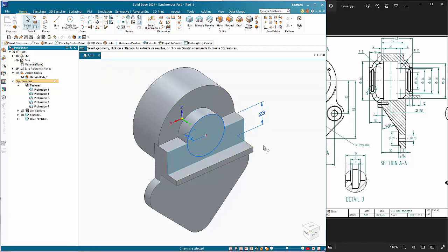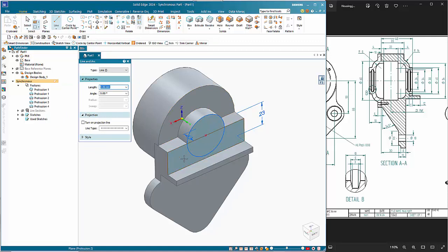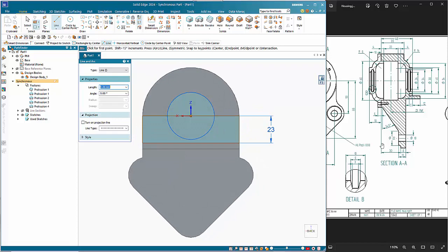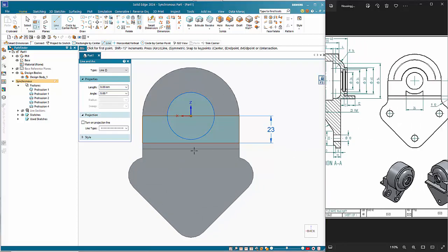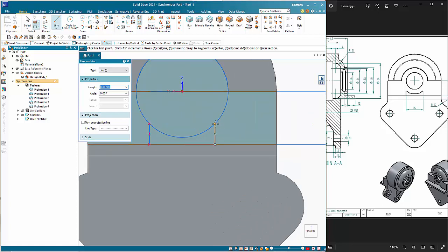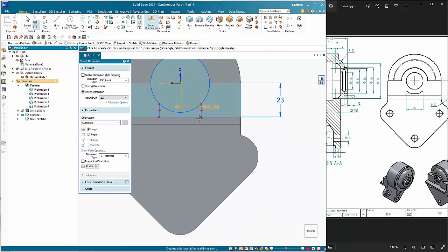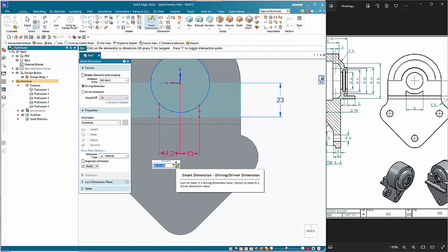So the next step is there's a cutout in the bottom here. So again, I can actually just draw some lines on here. So F3, and the distance on here is 26 wide. So I can just draw in two lines, making sure that there is a point on connection on there. So you've got the cross, which indicates a point on at both ends, and then I can add dimensions in here. So 13 that way, and it's got to move the line because it's key to the coordinate system, which is immovable. So that creates my region in here, and the depth on here is 5.